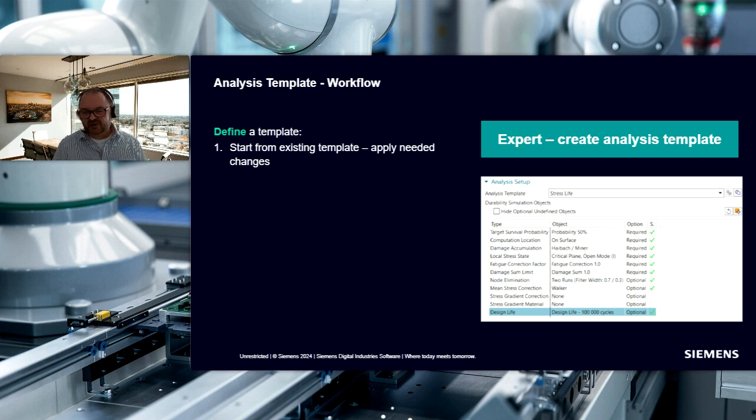Once you say, okay, these parameters I want to use for my application, exactly those, for example, a special mean stress correction method, this is Walker, which is typically used in aero industries quite often, or any of the other methods used here. So you define this setup, meaning a combination of the stress life method with all these parameters which fill into the method. That's the first step you do, you define that.